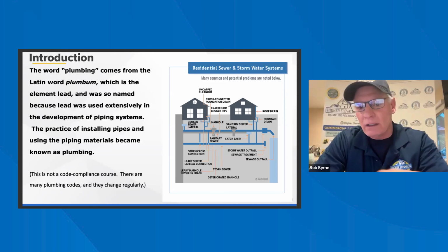Sometimes when you're in the basement and you're looking up, you can see underneath the tub, you can see a lot of the drains. So that's always a good place to look. Water pools and jetted tubs, you check the functionality. If you look on the right, that's an access panel. A lot of times we'll do whirlpools or jetted tubs or jacuzzis, and they don't leave you an access panel. So if you have to work on the motor or something like that, you can't do it. It's a silly thing. So when you have this type of whirlpool or jetted tub, always look for the access panel.